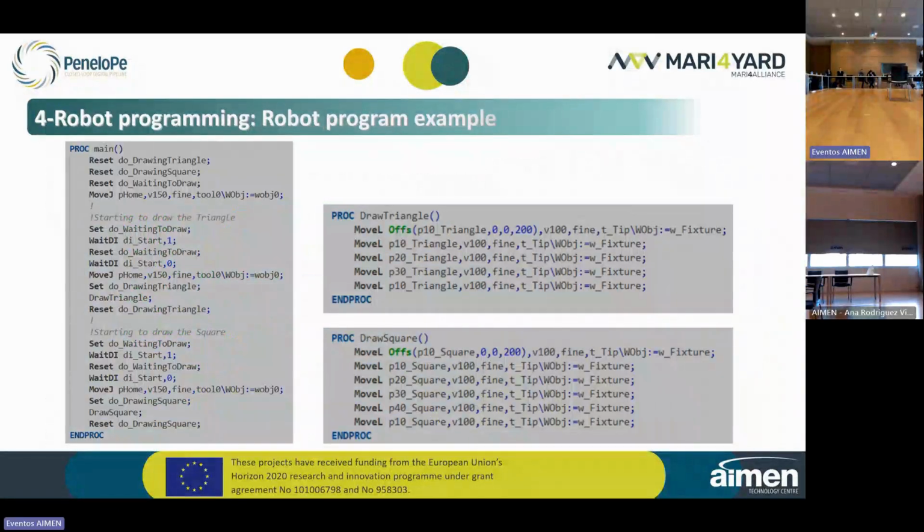To finish, I want to show you a robot program sample with three different routines. The first one is the routine with the name main, as we can see here. Inside of this main routine, we can see different instructions that will be executed in sequence when we want. These instructions don't exist inside of the main at the beginning.